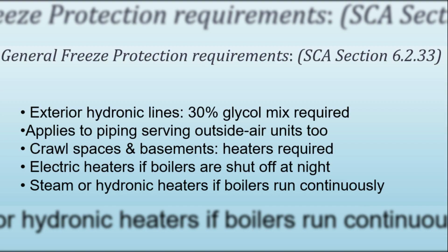Basements and crawl spaces also need to be protected. Heaters should be installed to keep those spaces from freezing. If the boilers are turned off at night, electric heaters are required. But if the boilers stay on continuously, steam or hydronic heaters can be used instead. These measures help keep the system safe and reliable during cold weather.